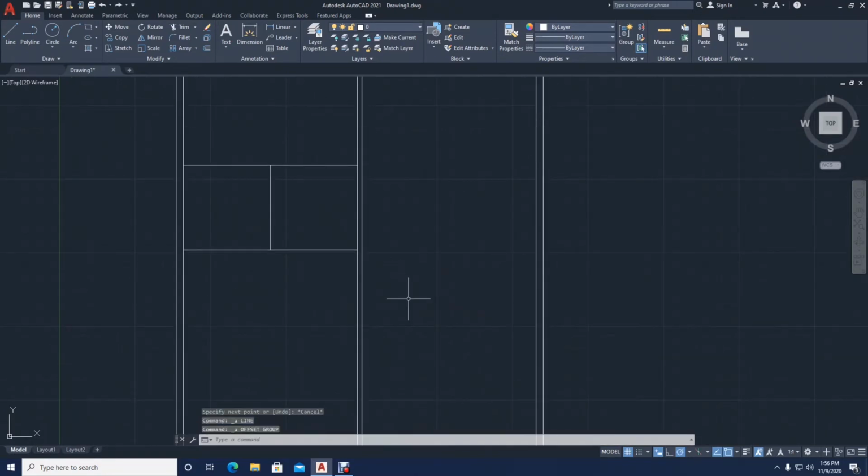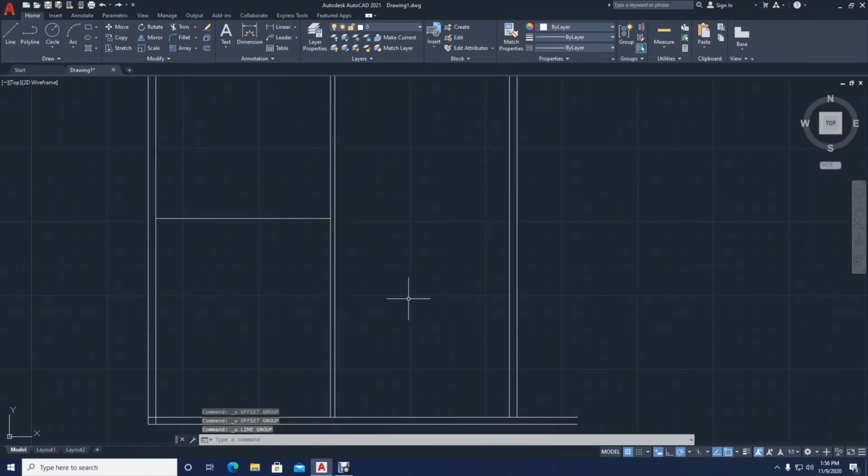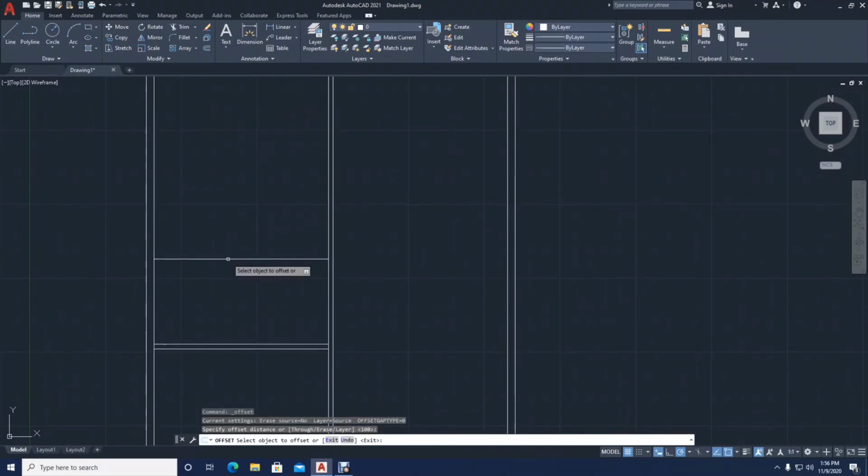So that's why you should always, after drawing the line that separates the rooms, draw the wall thickness by offsetting the wall in the direction that you measured. So I was measuring upwards, I offset upwards. Now the next room will be the bathroom, so I'm going to measure 1,800. Then I go across. Then I'm going to offset that measurement 100. And since the 100 has been set, I just press enter. I don't have to retype the measurement. I'll only retype the measurement once I'm changing the measurement.